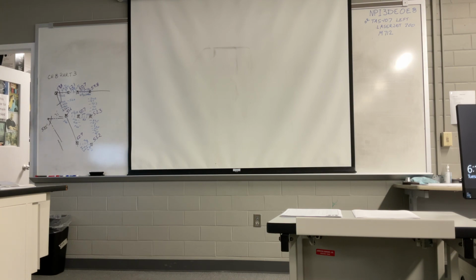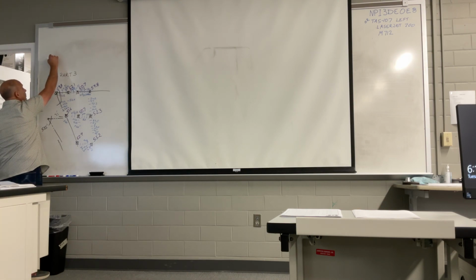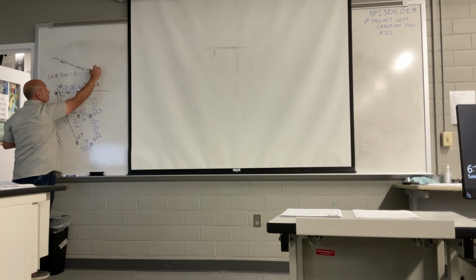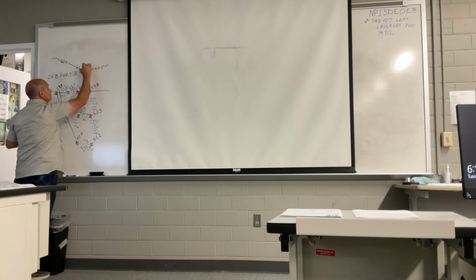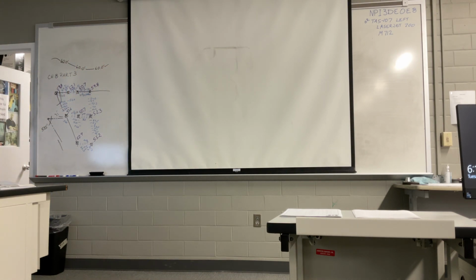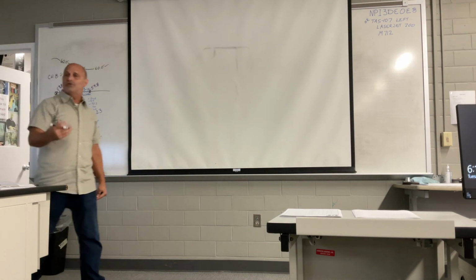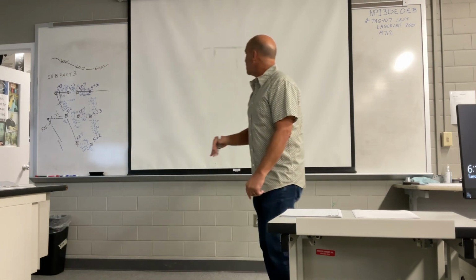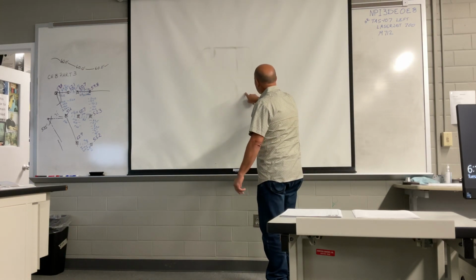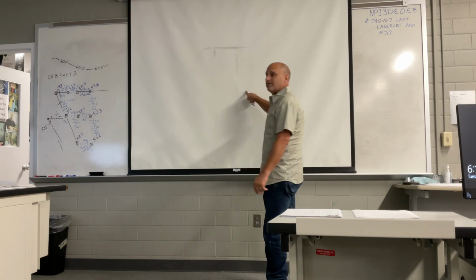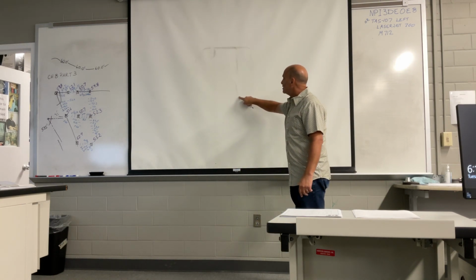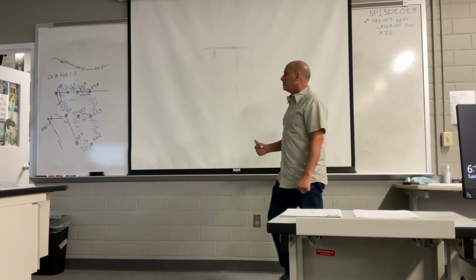When you're doing and labeling this drawing, you don't want to have a contour that is labeled like that. We're not gonna do kind of a stitch line, it's just fill those contours up. Your contour, and ask me, shoot me a PDF, ask me if you have too many or not enough. Basically, when we get a contour drawing finished and someone's looking at that contour drawing and they say, this contour right here, what elevation is it? It should be easy for them to track it in one way or another to find that written elevation.